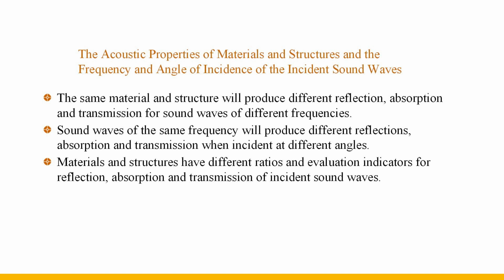use. Sound-absorbing materials and structures are widely used to solve acoustic problems in places with high sound quality requirements, and used to control noise in general buildings. The physical quantity that characterizes the sound absorption capacity of materials and structures is the sound absorption coefficient. The sound absorption coefficient is between 0 and 1. The larger the value, the greater the sound absorption capacity.